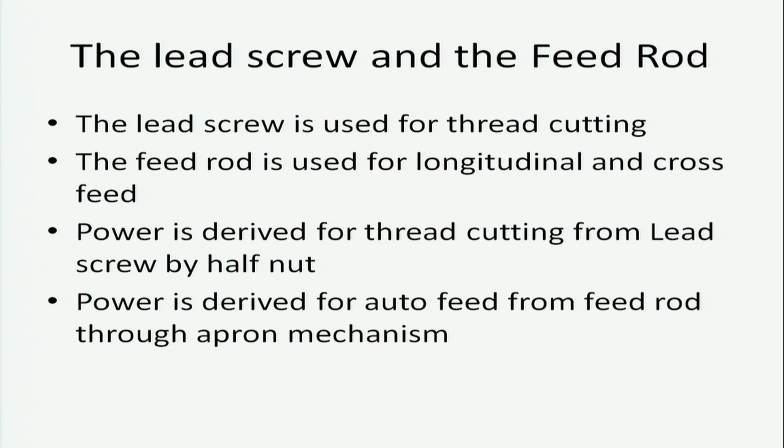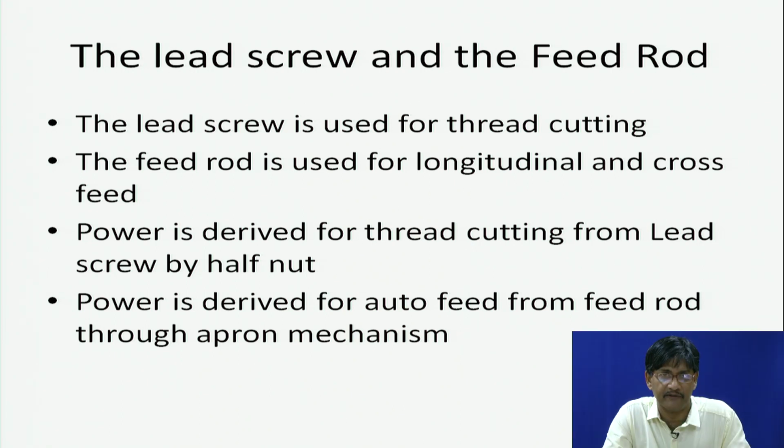It cannot be used for both at the same time. So, the lead screw is used for thread cutting, and the feed rod for longitudinal or cross automatic feeding. Okay. This is the basic difference.